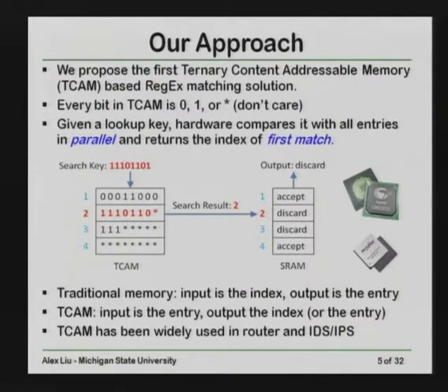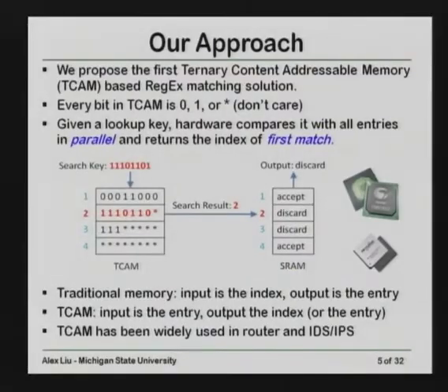We proposed the first ternary content addressable memory based regular expression matching solution. Ternary content addressable memory is short for TCAM. Every bit in a TCAM is 0, 1, or star, so there are three possible values, unlike normal memory where a bit is only 0 or 1. Given a lookup key, the TCAM hardware compares this key with all the entries in the TCAM in parallel, and then returns the index of the first match.